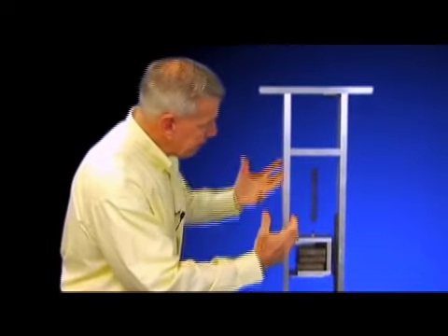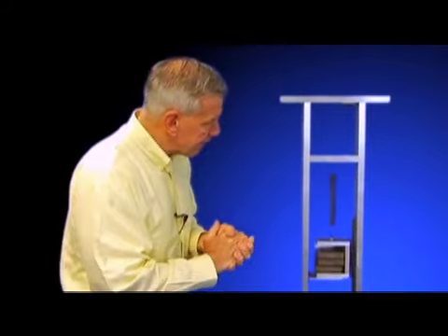So the spring is a pure spring. And indeed, it's also a tension spring that doesn't compress, and there's a certain amount of pretension in that spring as we described. So I'll treat the spring as being pure. I'll also treat the spring as being linear. Now, this is not linear in the sense that the bearing is linear, which means translational motion.